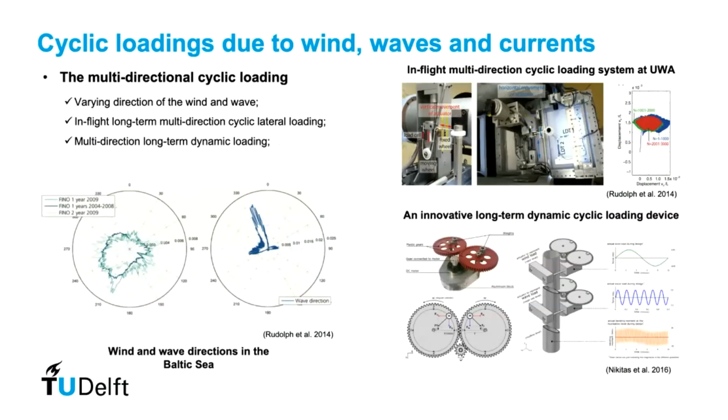One of them, for example, is this gear system, where you have this kind of Swiss clock, being in Switzerland, where each of the gears is rotating and you change the masses along each of the gears. By changing them, you can control the sinusoidal load with great precision. So this is a beautiful machine that allows testing the orientation of loads with great control, both in the intensity and direction. As I said before, the purpose here is not to reach failure by a single load, but to explore the effect of cyclic loading on the degradation of the shear behavior of the soil or the degradation of the soil structure interaction.